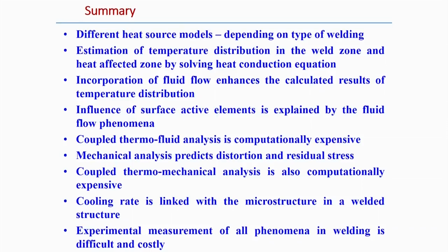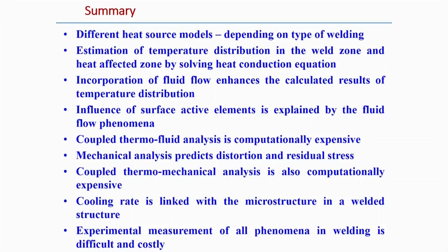Next was estimation of the temperature distribution in the weld zone and the heat affected zone by solving the heat conduction. We have discussed that the temperature distribution can be obtained by simply solving the heat conduction equation with proper boundary conditions. Of course, incorporation of fluid flow gives more precise results of temperature distribution, and the material flow is better represented if we consider fluid flow in the welding process as compared to only heat conduction analysis.